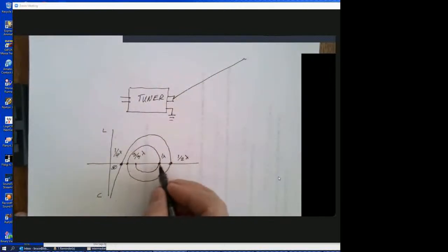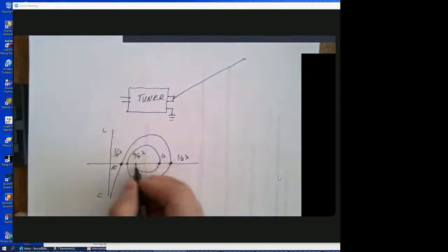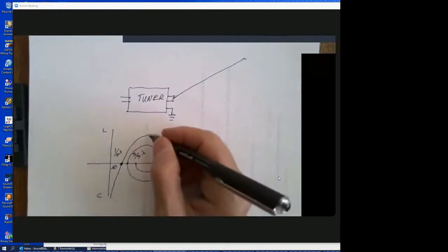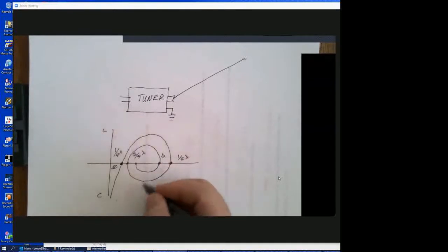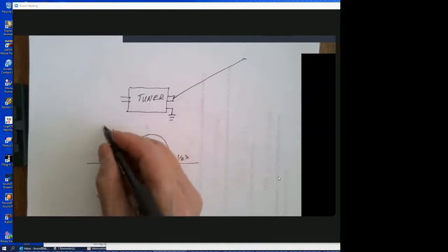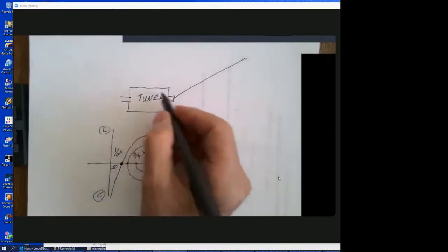As you go up in frequency, where the antenna is becoming multiple wavelengths, these begin to get closer and closer together. Notice that if you're not on a perfect frequency, if the antenna is not a perfect harmonic length, you will get significant series inductance and capacitance, which affects your match, and that has to be made up for by your tuner.